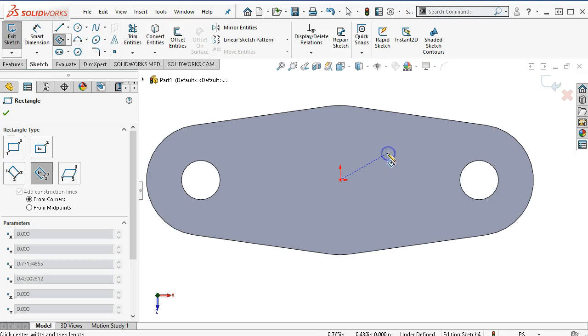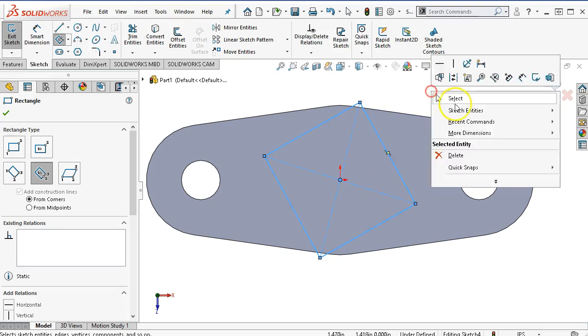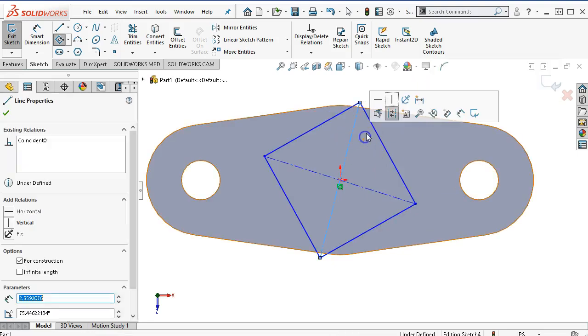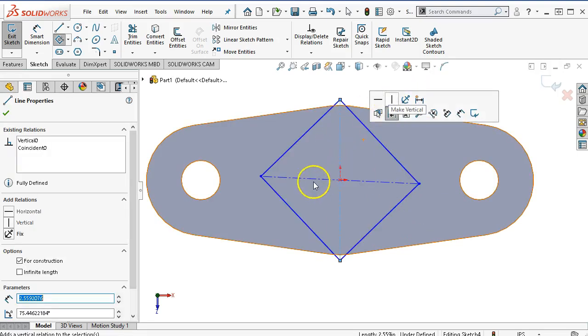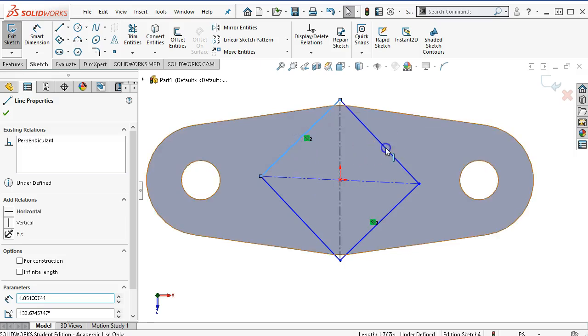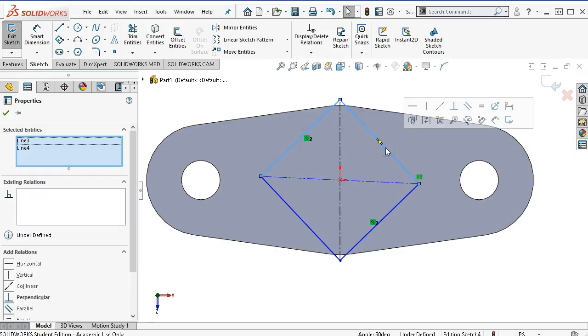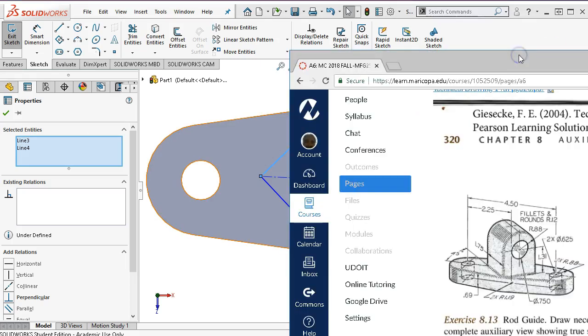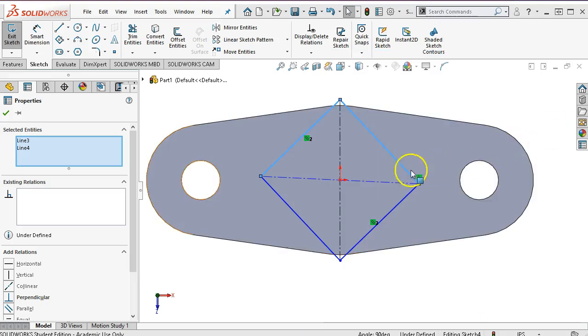And so when I drag out some distance and then drag the dashed line, that will give me my rectangle. One of those will be vertical. If we make the two sides equal, which they should be, we have a radius of 0.88 on the front nose of the part and a depth of 1.75. So we're going to stay with the 1.75 for both dimensions.